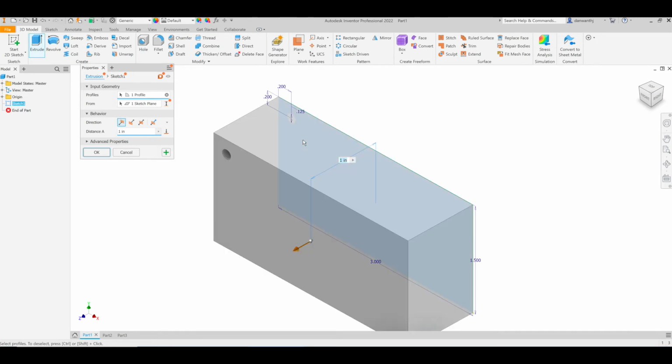There we go. As you can see, there's a keyhole. The hole is extruded, but there's nothing in there. The reason is I haven't selected that sketch. I've only selected one profile of the sketch, and that's the rectangle, excluding that circle that we drew. So let's go into this, and we don't want it 1 inch. It's really, really thick. We're gonna go over to 0.25 inches.